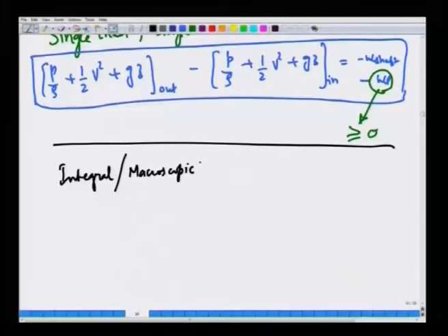We are not going to worry about detailed variation of flow quantities such as velocity or pressure at each and every point in the fluid, but we are essentially doing a balance over an entire equipment. So, they are sometimes also called macroscopic balances, which we refer to as integral balances. We have 3 equations for mass, momentum and energy.